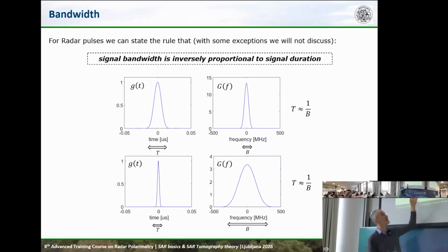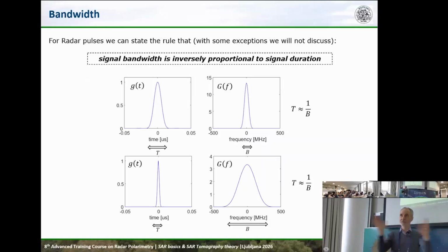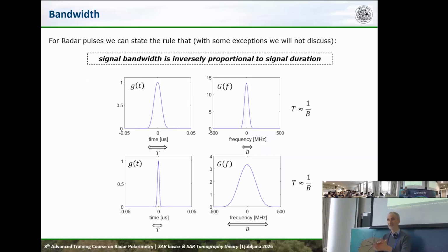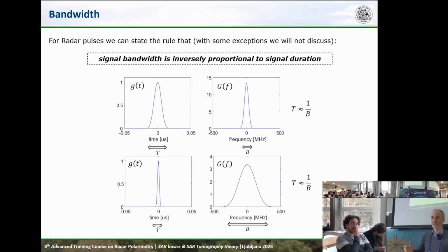So typically, a signal that is long in time has a narrow bandwidth, and a signal that is short in time has a large bandwidth. When I said before this is short in time, I said that this quite likely contains frequencies from, let's say, 40 hertz to a few kilohertz. So for an acoustic signal, a very large bandwidth, because it is a very short sound. My voice, which goes much slower, has for sure a narrower bandwidth.